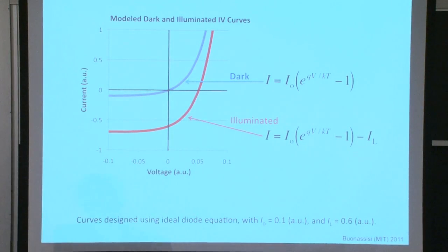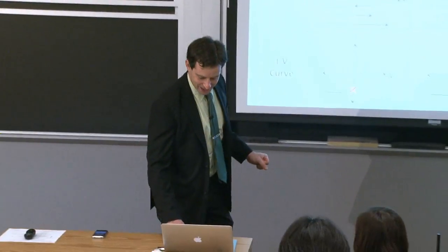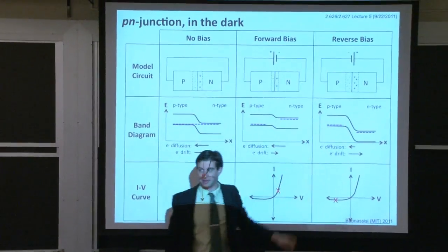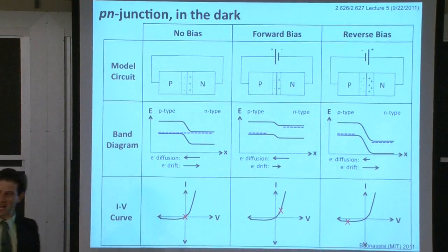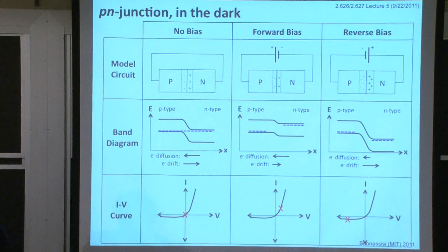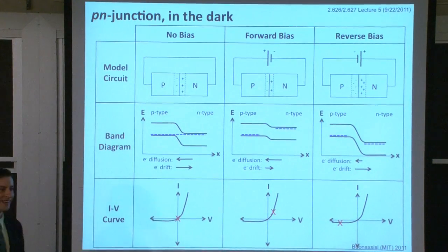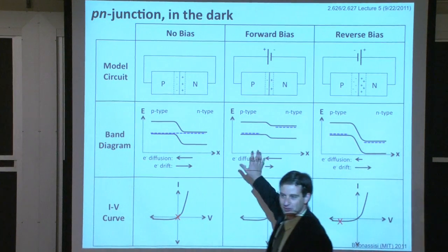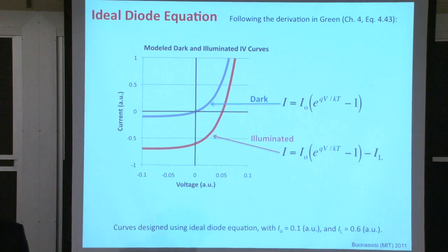And we have as well bias to the solar cell device, right? So we have a bit of a combination of the last two slides, right? In this case, we had in the dark, we were biasing our solar cell using the battery. And in the illumination conditions, the light itself was causing the solar cell to become forward biased. But we can add a battery to sweep the bias condition of the device, right? So even though we have a natural biasing of the solar cell by the light, we can force the solar cell under different operating conditions with the battery. And so that's effectively what's happening right here: you have a combination of both simple scenarios that we just looked at. And we're building on those components to really understand the larger system.